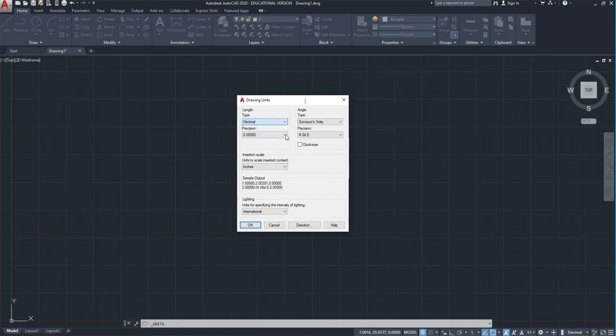So under decimal, okay, this precision looks pretty good. I can't explain to you the terminology used to identify the precision in surveyor units, but I know that I need more precision than is illustrated right there. I know that I need this precision. It's the third one down, and it shows degrees, minutes, seconds, and then direction, okay? So we want to see a direction, we want to see that 0 degree, 0, 0, which is minutes, 0, 0 seconds, and then another direction. Okay, that's the precision we want to see. I wish I could sort of zoom in on this, but it won't really let me.